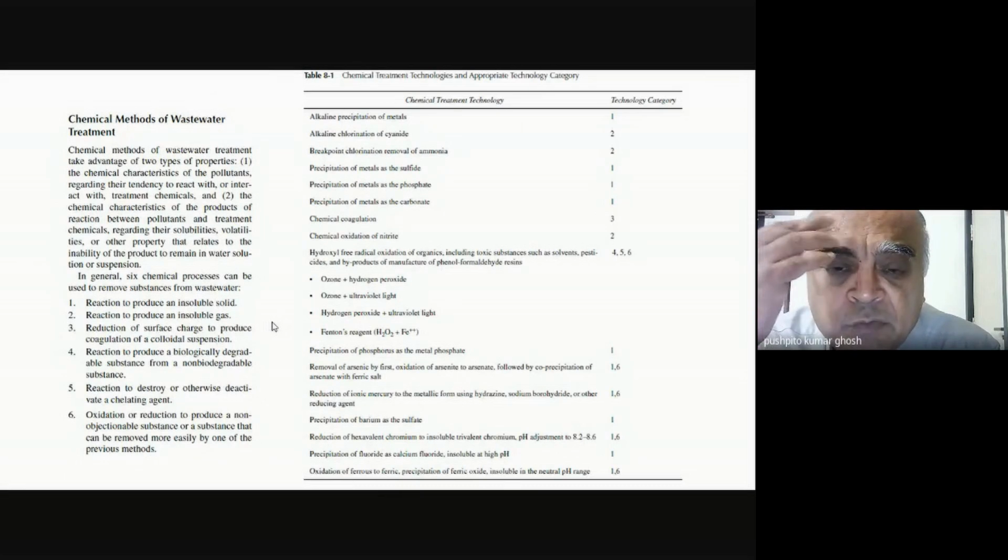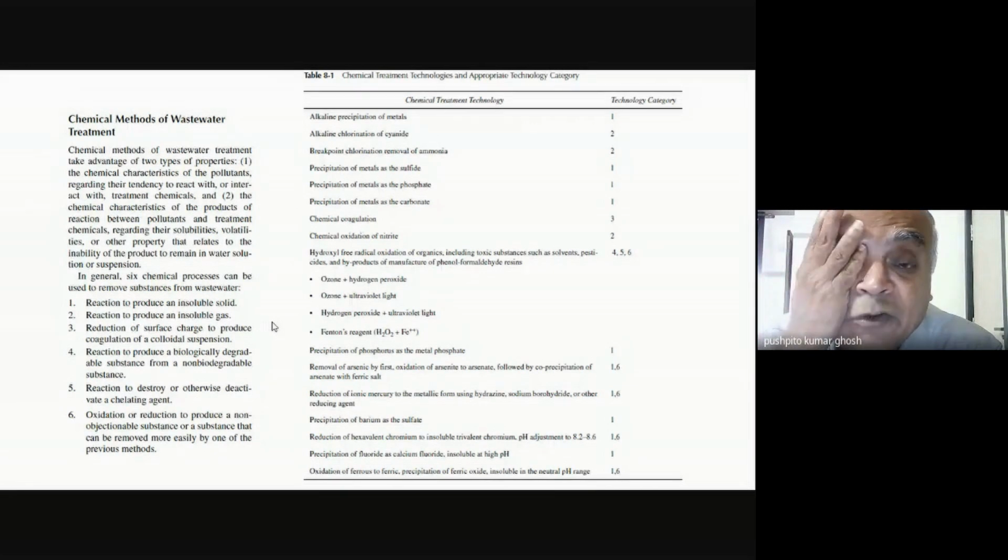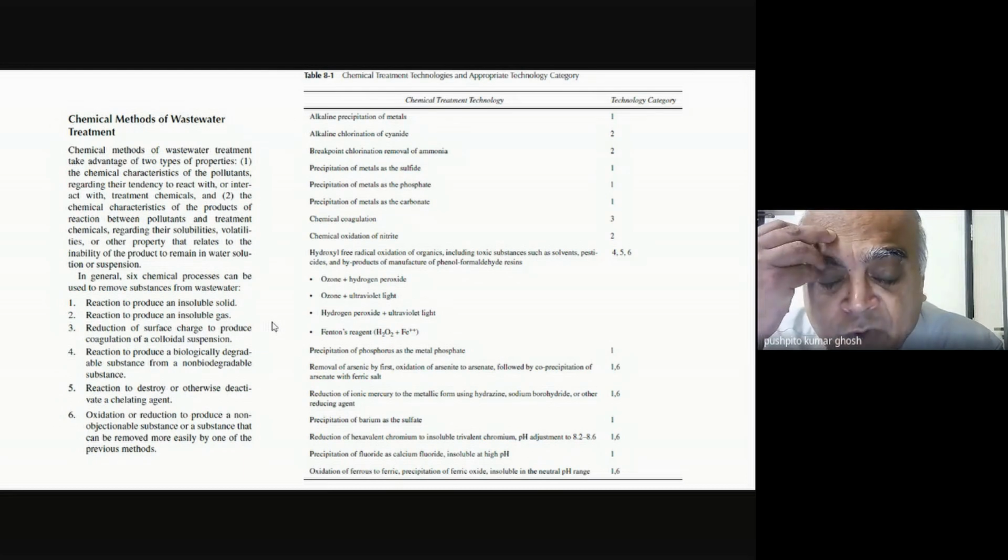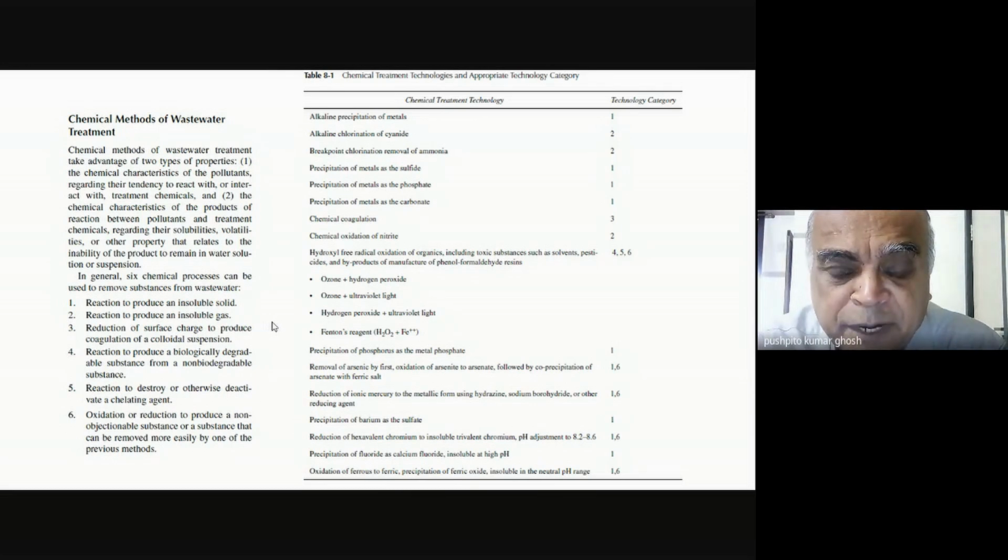Now, when you analyze the problem, what you may find is actually that the COD is not very high. That stuff is also actually not necessarily very toxic. But the objectionable part is the color. And the color is what? Color is only a chromophoric effect, right? So if I can destroy that chromophore, then the color may disappear.